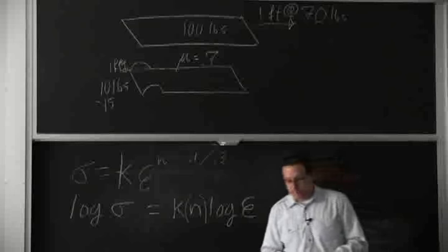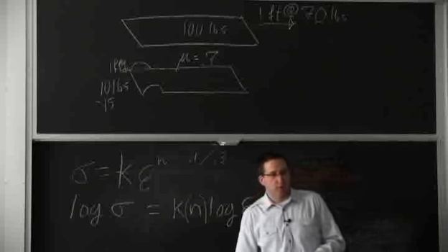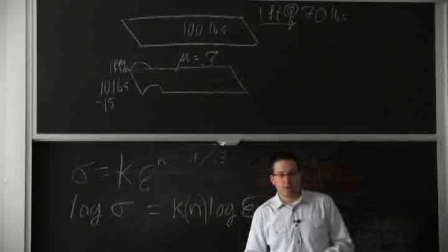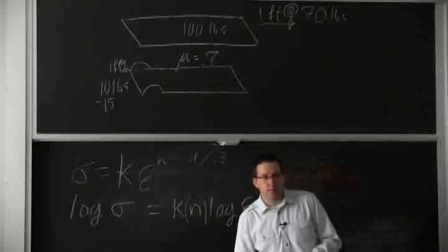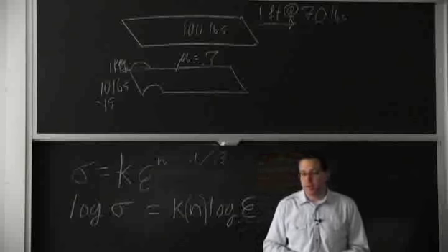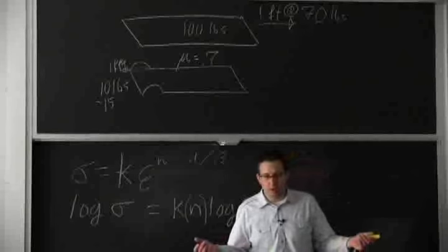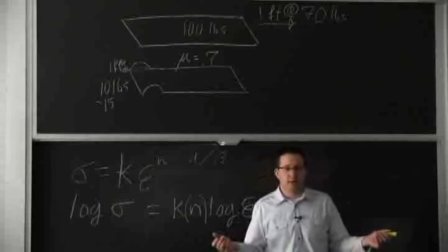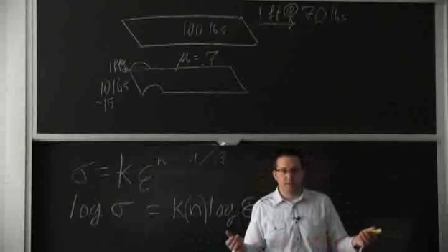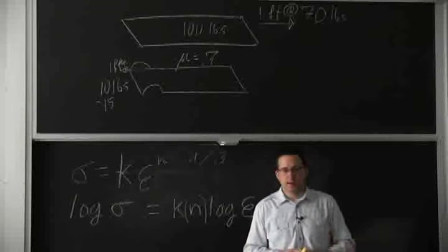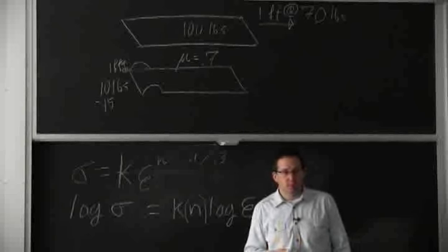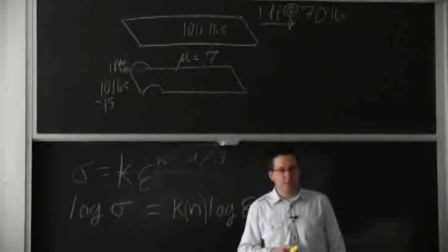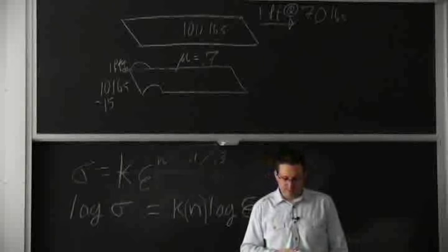We can make a big advantage of work hardening in products. Copper pipes, for example, tend to be very soft unless you cold draw them in the final step of making the tubing, and that's how we can put more pressure in them, or they don't sag. There's a great variety.